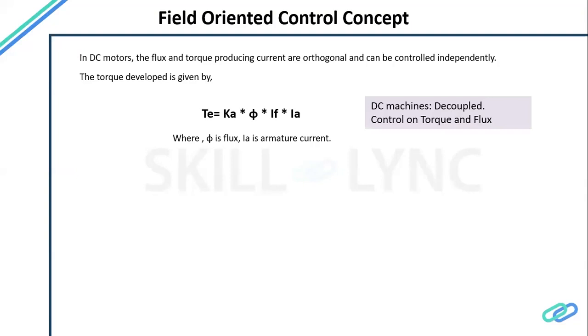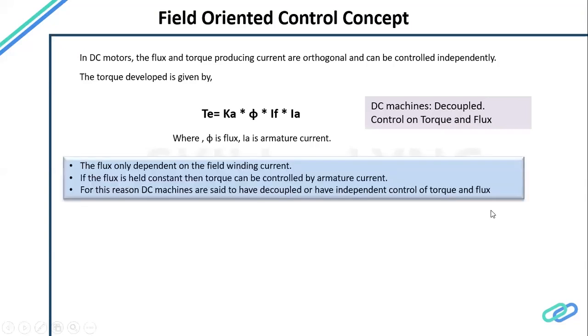So it's a trade-off. If we can decouple this, we can really control whatever we want at high speed. At high speed, the back EMF is so high that it may be more than VDC, the bus voltage. So to do that, we demagnetize the magnet, or we increase the ID.